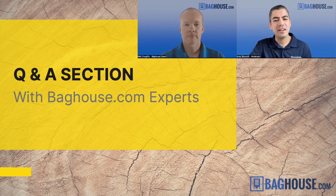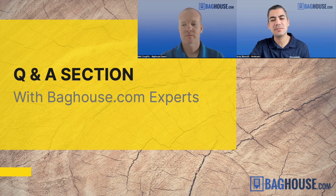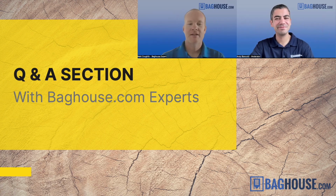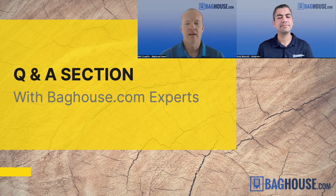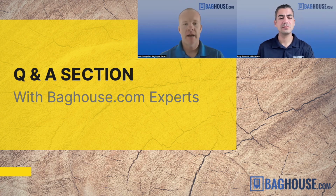Excellent. The next question: are floor sweeps a good idea in woodworking facilities, or can they create problems in the dust collection system? This almost sounds like a loaded question. Floor sweeps are very convenient for shop operators because when they clean up their shop, they just sweep everything into the floor sweep. That's great. It's convenient. I would want one if I was working a saw all day. There is definitely a downside to floor sweeps, and that is that everything that gets swept up into them will go into your baghouse, into your dust collection system.